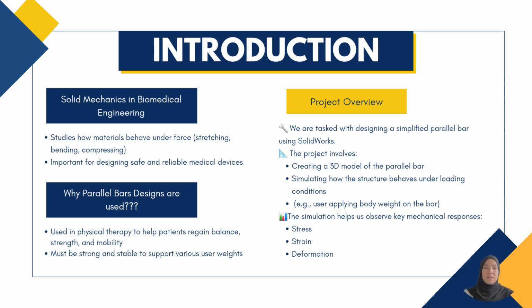We choose parallel bars because they are common in rehab. They need to support different user weights safely. So the design must be strong and reliable. In this project, we used SolidWorks to design a simplified parallel bar. We made a 3D model and simulated how it reacts when someone puts weight on it.